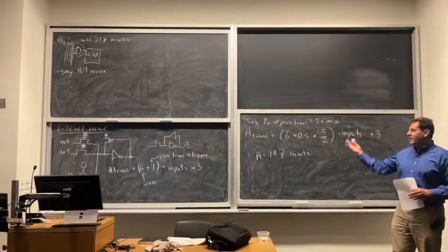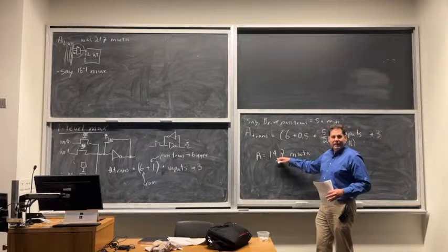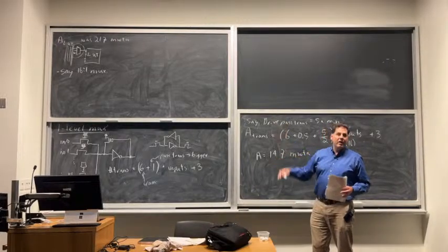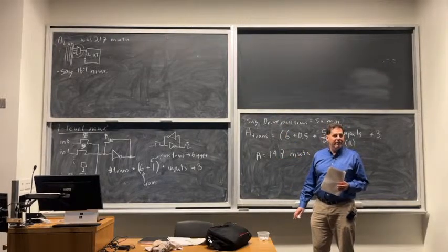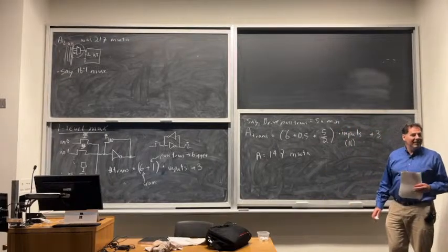Connect the inputs to it. And I'll take 4 of these. I'm going to have 600 units of area, which is almost 3 times the size of my LUT. So, somewhat painful, right? Programmable routing is big.